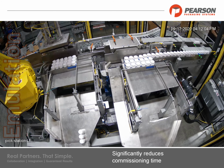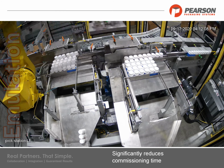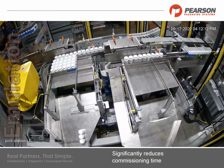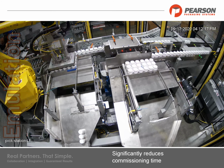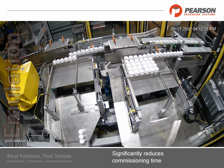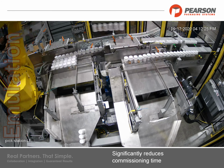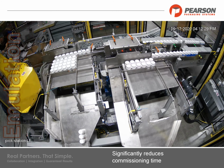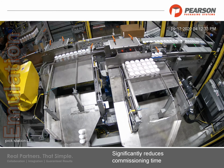Finally, you can see the real operation of the machine and how this functions with the code that was developed in emulation. One thing that we will point out here is that when the code was dumped into the real processor, we tried to execute and there were some errors and things didn't behave as expected. Through a quick analysis, we were able to identify two sensors that were wired backwards, and two sets of valves that were also plumbed in reverse.